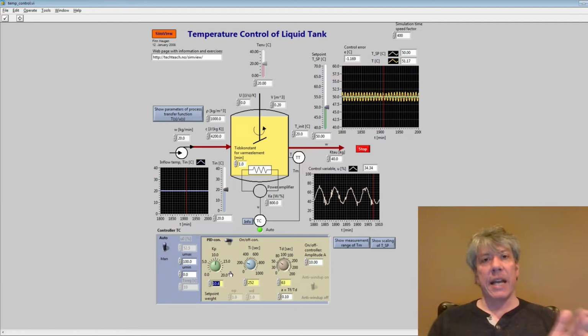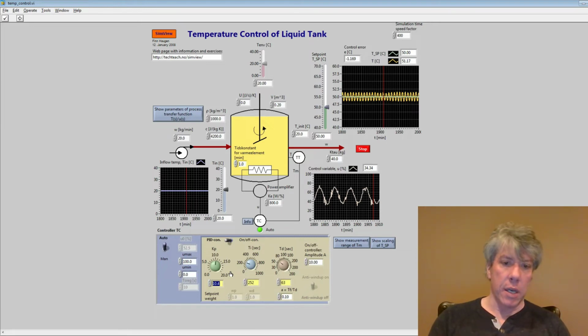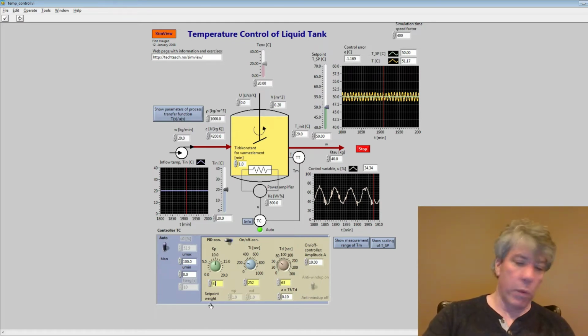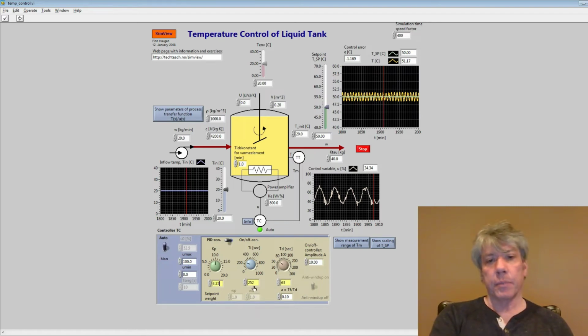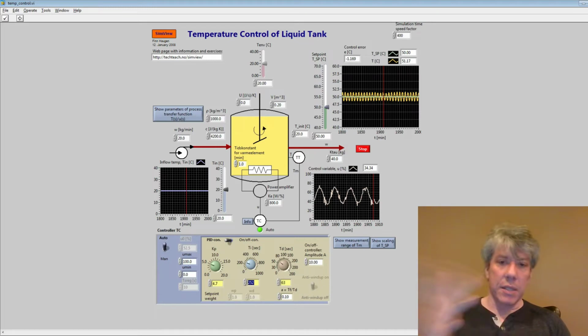But if I wanted a full PID, then I think the divisor for Kp, don't hold me to it, I think it was 2.2. So if we take 10.4 divided by 2.2, then I would need a gain here of 4.72. Now where you get into trouble is with the units on Ti and Td. I'm operating off of memory here. I'm pretty sure that for a PID controller we need Ti equal to the ultimate period divided by 1.2, and then Td was the ultimate period divided by 8. I don't remember. I don't have it in front of me. Let's just say that's the numbers. You can look it up on the slides.